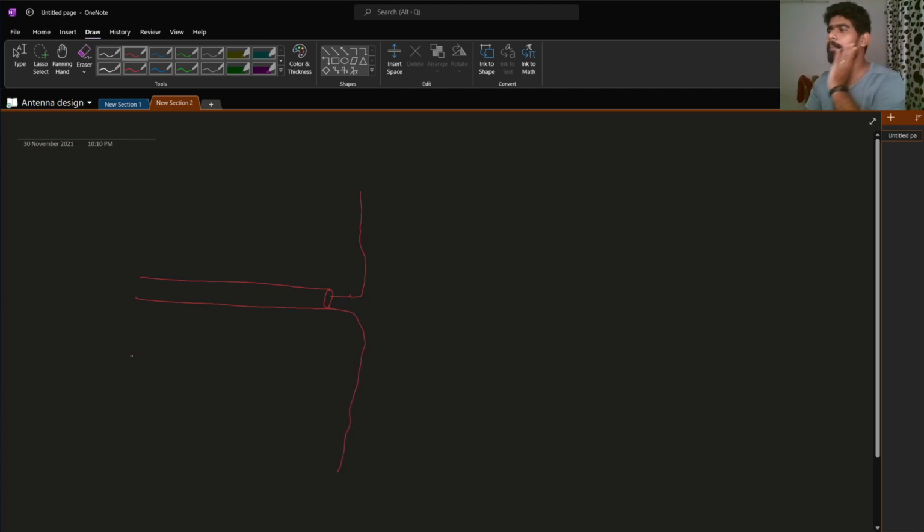But when you fabricate this, there is some issue. What people usually do is go directly to a 3D simulation like HFSS or CST, and they draw the tube through two wires like this, and they put a lumped port here and do the excitation with the lumped port. So the issue is that when you feed like this, it's a perfect feed. The balance issue does not come up.